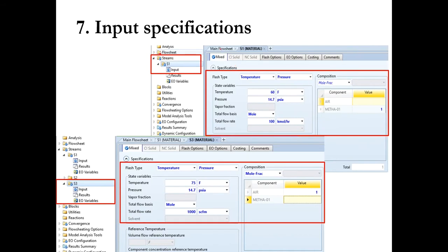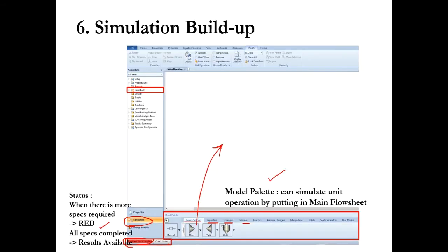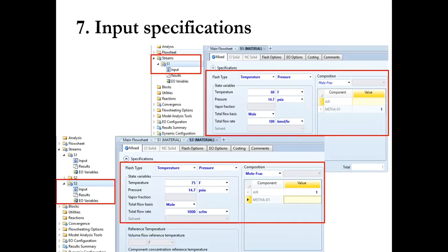So the first thing you need to do is select the material stream. If you see here, a lot of streams are present: material, energy, work stream. So you will select the material stream over here, paste it, and give the values of these material streams for methanol and water.